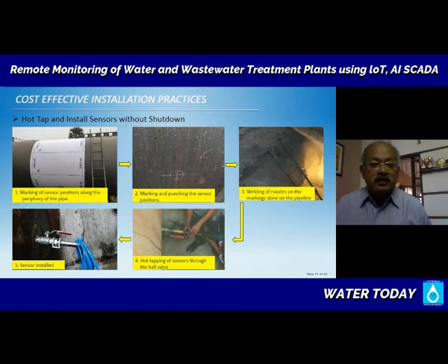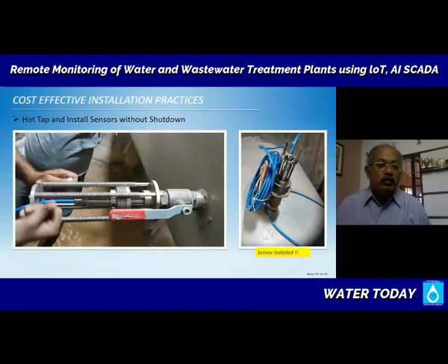And that is a pressure insertion tool that is being deployed. The water is under 4 bar pressure in that line, and we are inserting the sensor with a tool that looks like a jack of a car. We just turn the handle slowly, the sensor will go in place and settle down, and then you remove the tool and lock up the sensor where it is. That's the picture on the right hand side, a sensor that is happy, ready to function, installed. So this is how you install your metering without disturbing your water networks at all, even in very large pipes.